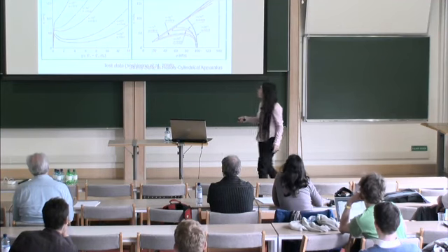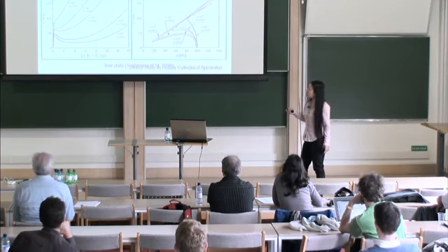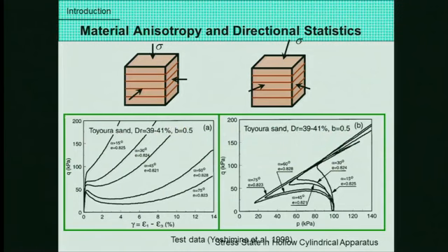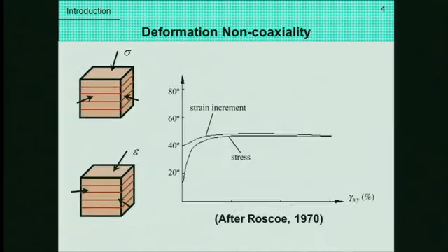I'm just trying to show you how soil behavior can be different when we change the loading direction. This is the undrained test, which is constant volume shearing. This set of curves is from experiments carried out on identical samples. The only changing parameter is the loading direction with respect to the bedding plane. You can see we can have a very soft behavior, or a very strong behavior. So we need to understand that, and then we can possibly model it.